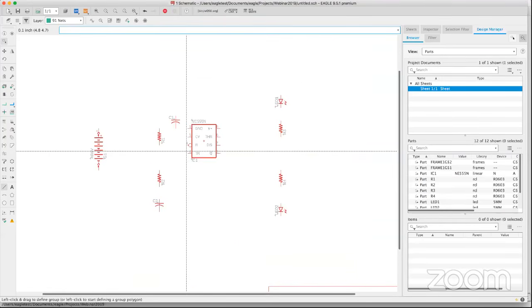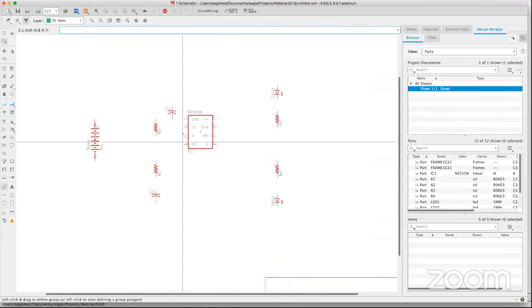So now I'm going to start defining connections. And when you define connections, of course, it's totally logical that you're going to think of the line command, right? Is that right, Jorge? Everybody, if you think you need a connection on a schematic, you're going to be using the line command. That makes total sense. It used to be worse because it used to be called wire. At least now with line, I found that more people have not made that mistake. When it used to be called wire, it happened all the time.